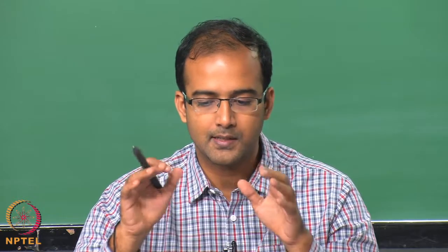So, therefore, fabrication of micro thermocouples is actually more challenging, but of course, in terms of response time and also the range of temperatures that you use, they are more versatile than the RTDs, because RTDs have a very limited range of temperature.